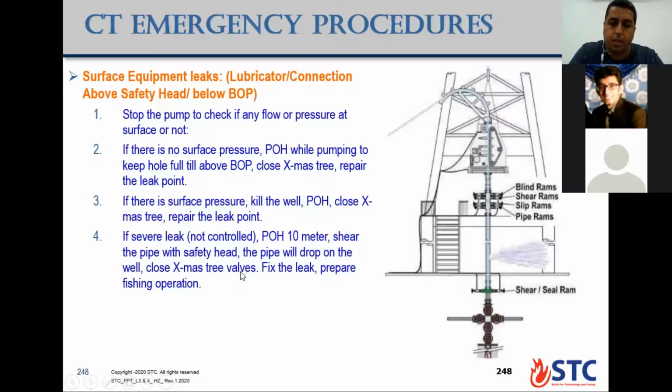But pumping through coil tubing would be relatively more feasible. If you want to kill the well, pumping through coil tubing would be more feasible relative to bullheading. But pumping through the coiled tubing will restrict the rate, and you need the kill fluid to start to enter the annulus. I think if we don't have high pressure, then we would go with coil tubing. Otherwise, we would go with bullhead.